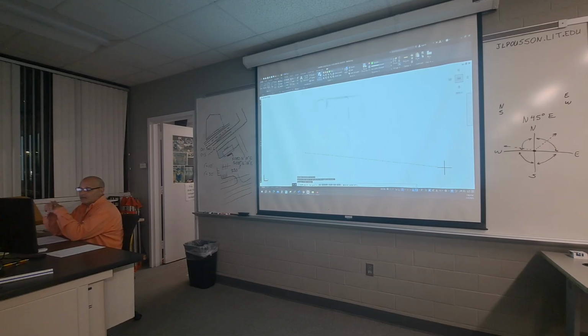So I look back over: at symbol, less than symbol, so my formula symbols are there. 410.65 feet, that number's good. South 8 degrees, 16 minutes, 18 seconds east, that number's good. I hit enter. Mr. P, I can't see where that line went, that's okay. Once again, at the distance, is less than, the angle. At 600 feet is less than my angle, north 73 degrees, 52 minutes, 39 seconds east.